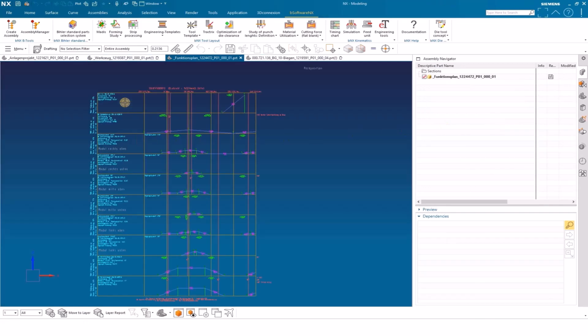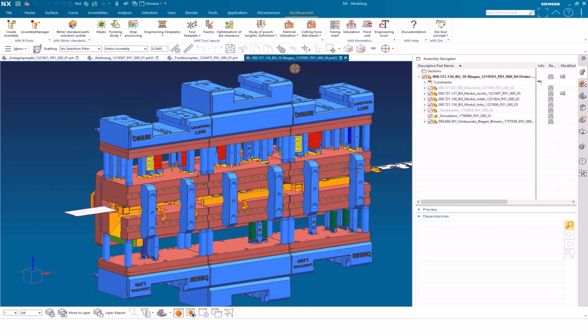In the timing chart, the movements are defined according to the VDI 2143 laws. The aggregates of the selected machine are selected. The NC driving profiles are exported for the VC1 control. The timing chart is also added to the simulation.